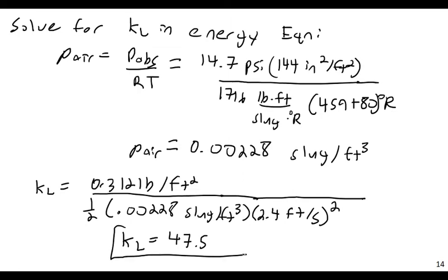And now once I have it for one point, I can measure the K. Once I know that, I can predict the head loss for any velocity change. So actually, in this case, we don't even have to plot a curve versus velocity. We can just go and calculate it directly.